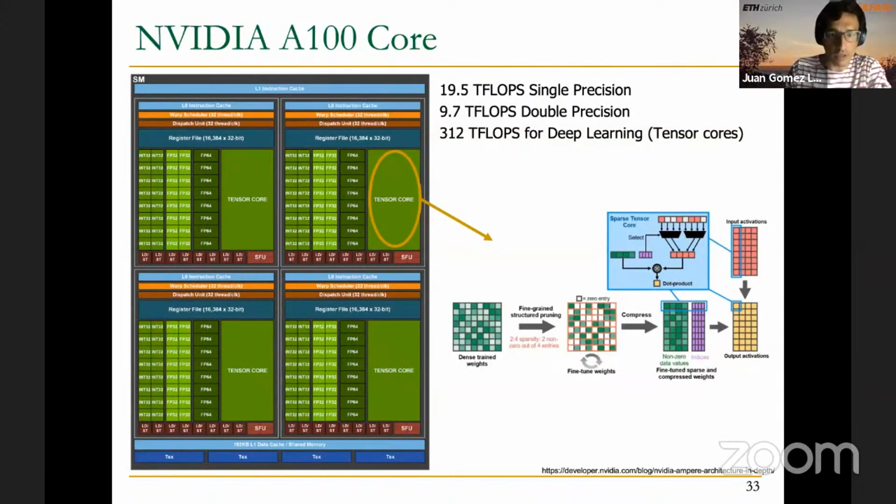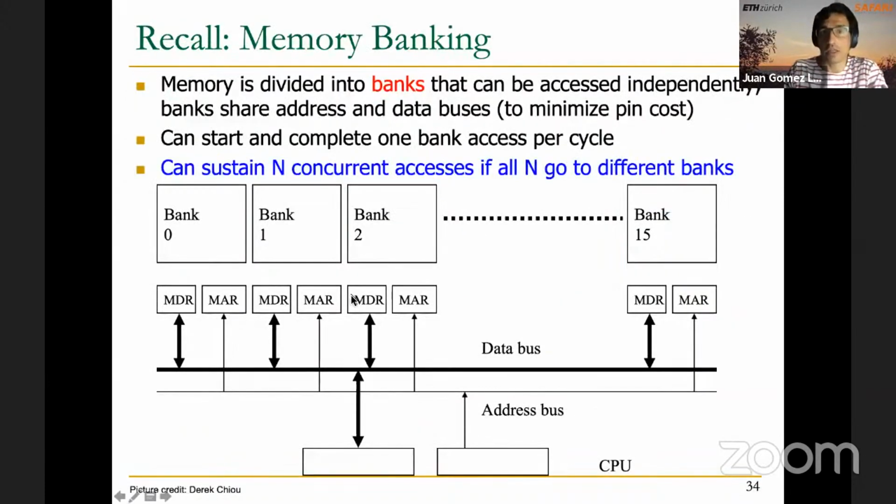I was just mentioning a few slides ago the interleaved or banked memories, and I mentioned the shared memory. This shared memory is a scratchpad memory space, meaning a kind of software-managed on-chip cache, because it's inside the GPU core, where we can store input and output operands that we read or write to memory. And this shared memory in the end is a banked memory, as I said, and I already mentioned that it's typically 32 banks, not 16 as in this example.